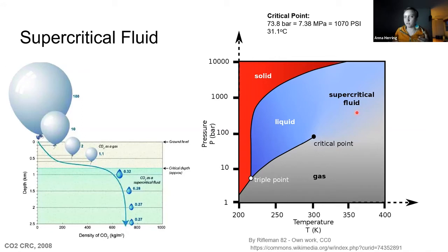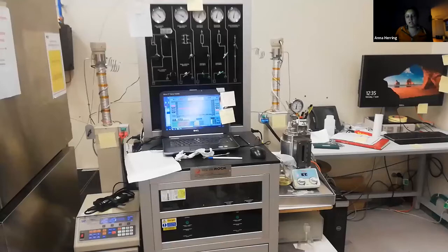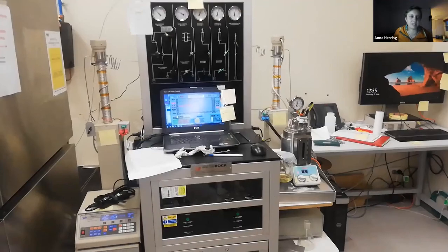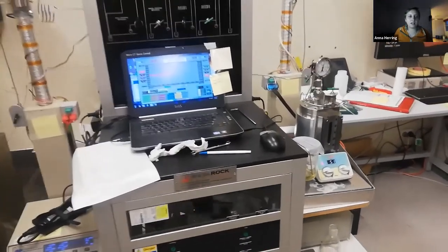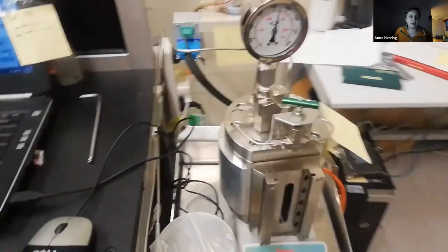The other fluid properties also change pretty dramatically with pressure or temperature. Things like viscosity and interfacial tension change if you change pressure or temperature even slightly. So for our experimental setup, everything needs to have the same pressure and temperature to keep that supercritical CO2 in the same phase and the same state. This is a video I took just the other day of our flow cell.